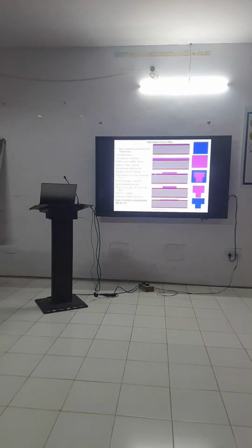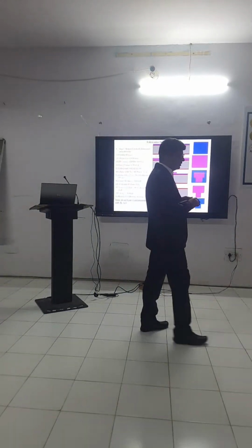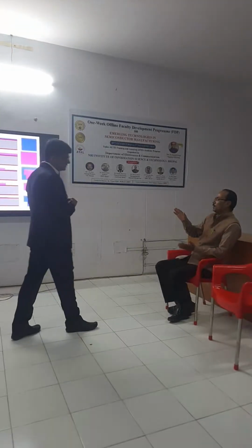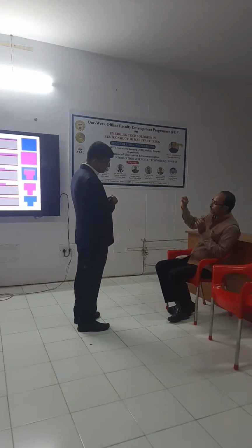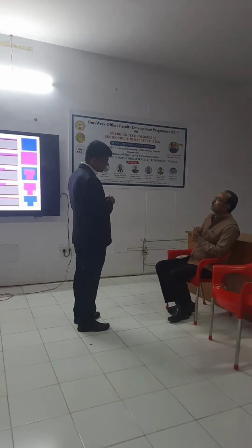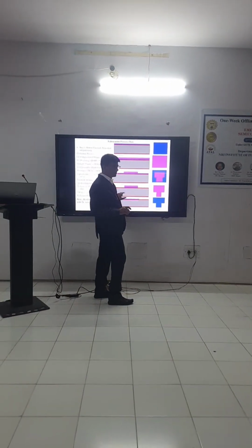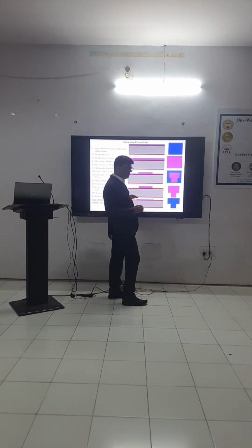So suppose you want to deposit the Bragg reflector in the substrate. Suppose we have the substrate here, and on that we have to deposit the Bragg reflector, the mirror layer. So what will we do? We already have this device without the metal oxide layer. First we will deposit molybdenum as my reflector layer.